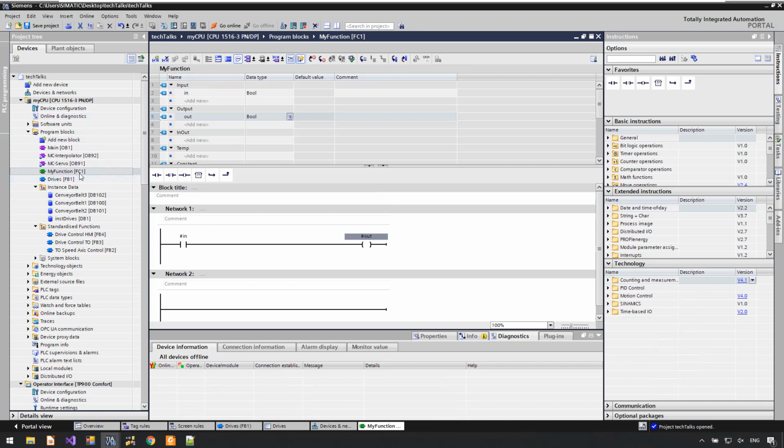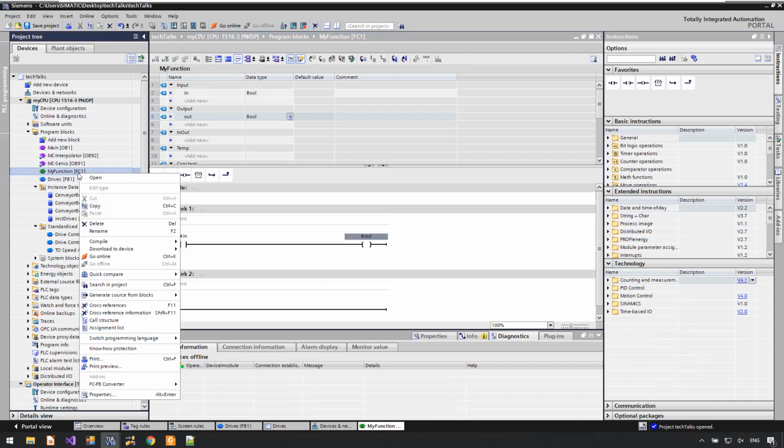So this actually allows me to fix it. If I right click, you can now see that we have this new menu, add-ins, and FC FB converter is the add-in that we installed. Currently it just allows me to go into settings, but as you see, if I trigger it again, it now knows this block is here, and asks if I want to convert it to FB. In settings, you can find some settings for the add-in. If it was a function block, for example, it would have statics. Then there's a question: what do I do with these statics? Do I remove them? Do I make them temps, in-outs? You can just set it here.